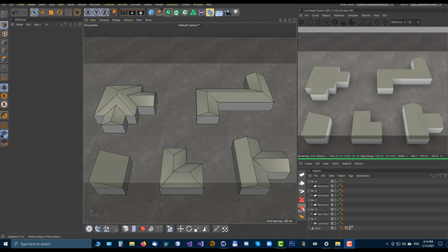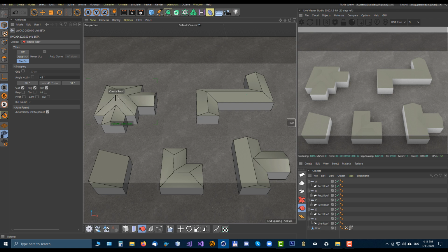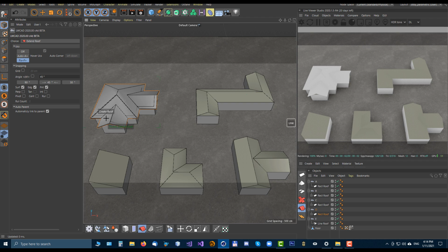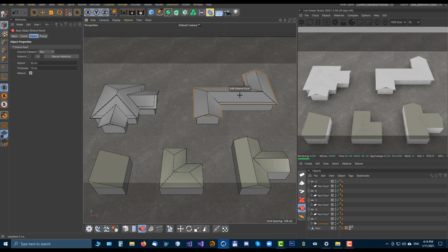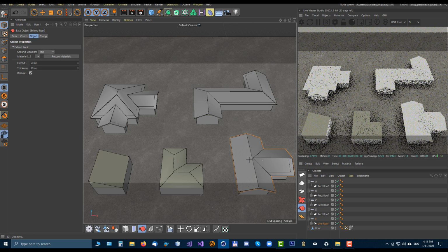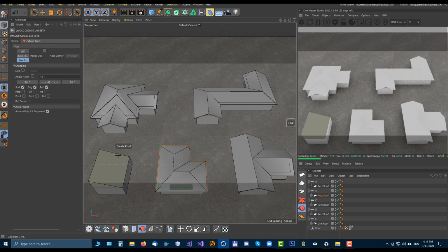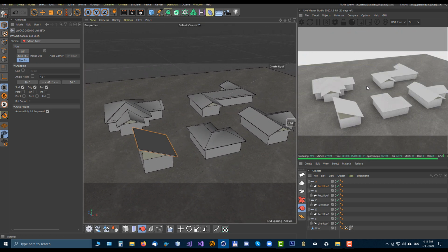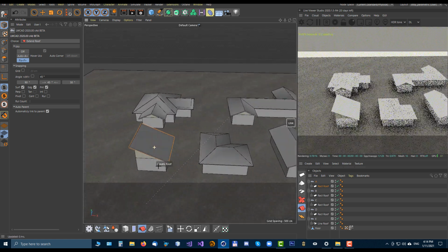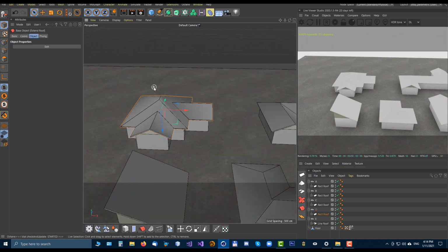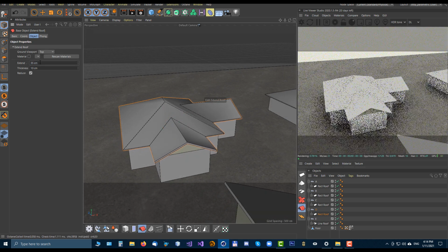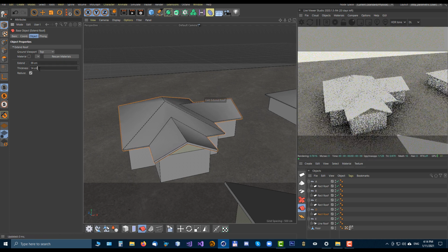And now let's do the extend roof tool. You activate it with automatic link. You just click on the roof and an extension is created. Right mouse button will end, and with the left mouse button you can attach to another. Right, left, right, left, right, left, and with 12 clicks you create the extensions of the roof to the existing roof. This tool is of course parametric, so you can adjust all the parameters. You can adjust extensions, you can adjust the thickness.